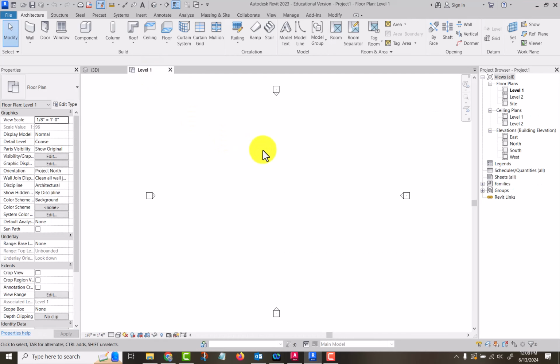I'm going to close it, and it's because I'm on level 1, which is an architectural level. I want to be on the site level. Now my points will be visible because in visibility and graphics, all that stuff is turned off on the architectural levels. Okay, so here's our surface menu over here, and we're going to go place points.